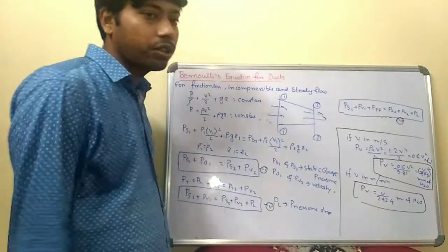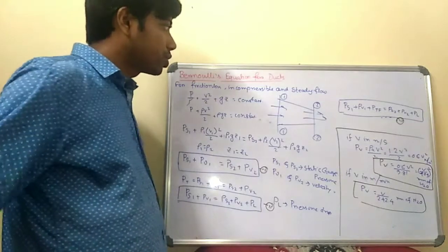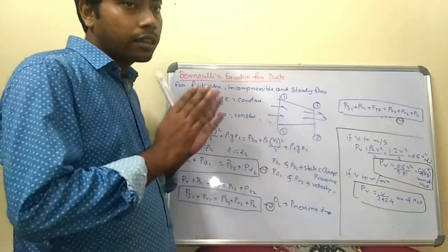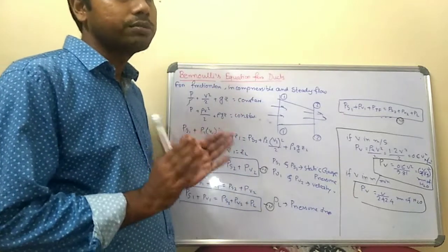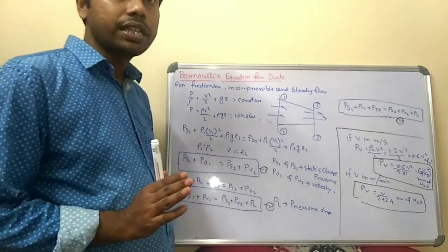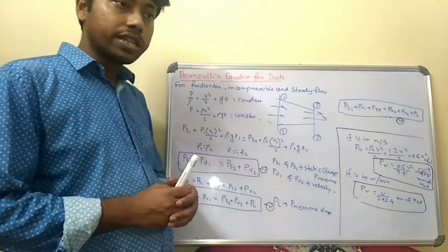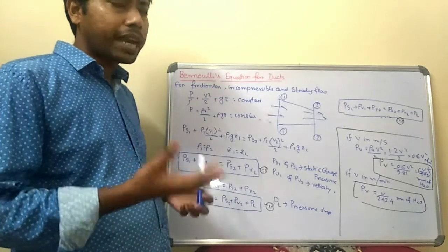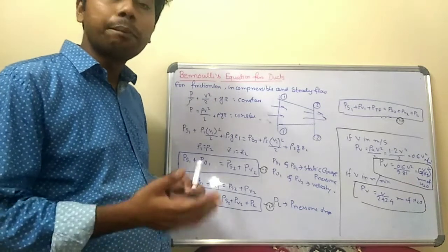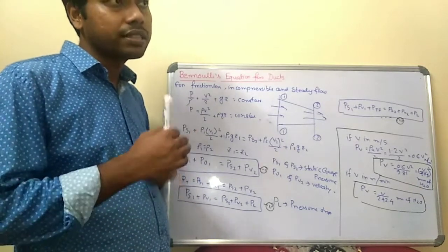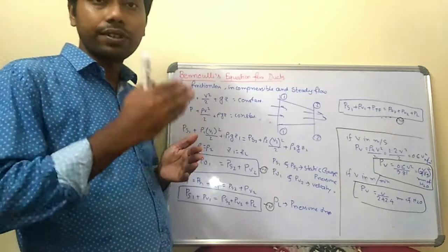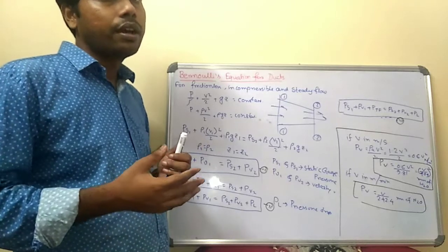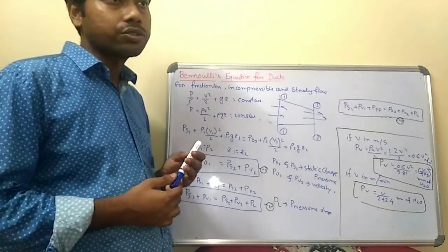So this is a small interpretation for the numerical. Bernoulli's equation should be followed in the duct, and there should be some pressure defined so that the air flows through the air conditioning system. And obviously, in practical or real cases, there are some pressure losses, because when the air flows, there is some friction within the outside or inside surface of the duct. So there is some friction loss, and when that happens, there is some pressure loss.